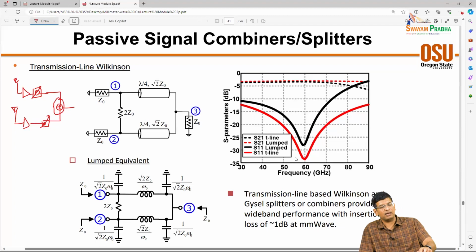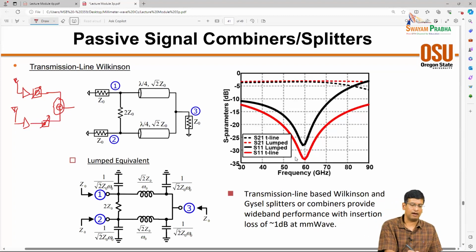It can simply be a current summation where you have over here a GM stage, right? And another GM stage. And all we are doing is just dotting the currents together into a load, right? This is possible. So this is an active summation approach, right?